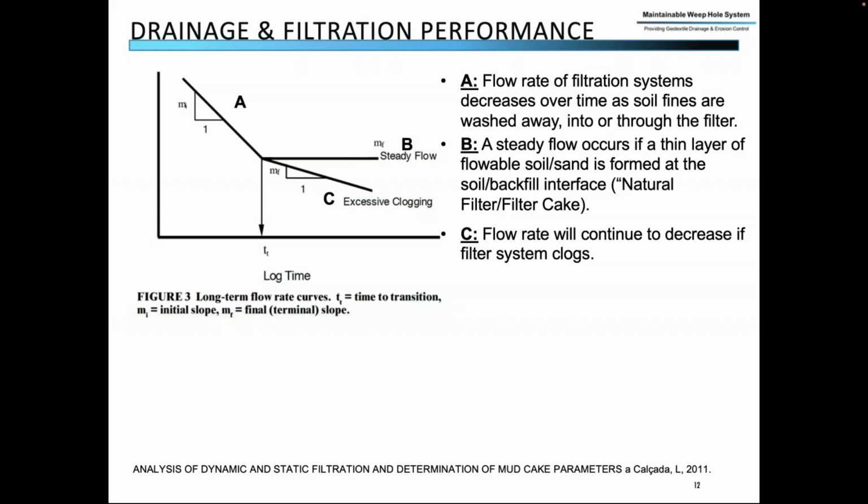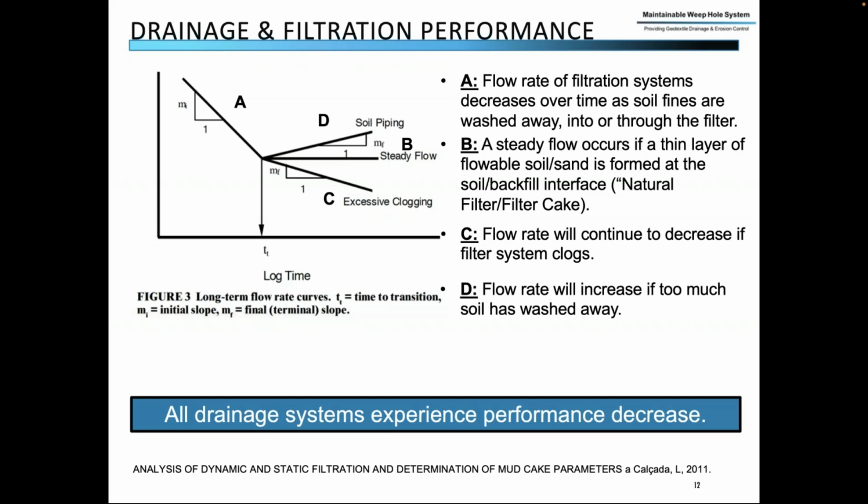And as the water stops, it builds up pressure, and then the water is going to find a way. It's either going to go around the clogged geotextile, or it's going to go through the geotextile, ripping holes in it, and then soil fines will pass out through the drainage outlet or through cracks in the wall, around the wall, under the wall. The soil is going to go out, and then that can lead to voids and sinkholes.